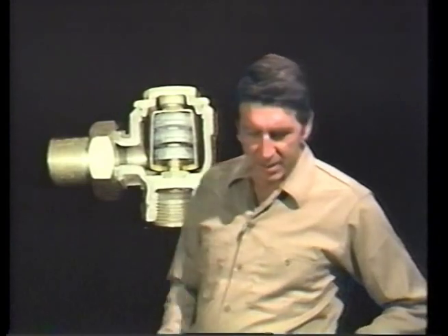In thermostatic traps, you will hear the periodic discharge of condensate as the trap cycles. Absence of sound may mean that the trap has failed shut. However, check the flow to and from the trap to be sure. If the bellows ruptures or the seat wears, you'll be able to hear the steam blowing through the trap.